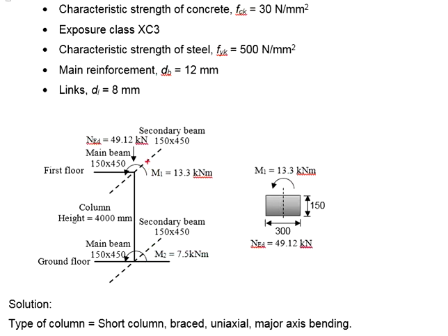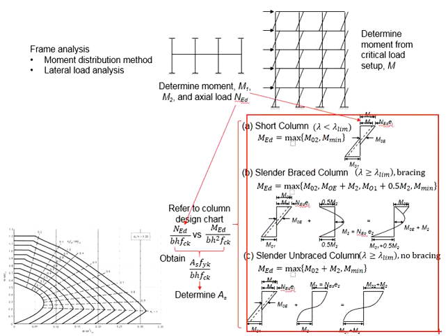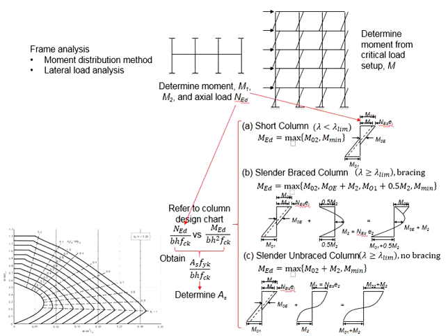However, these are the moments acting onto the columns. We are unable to take this moment directly as the design moment. This is because there may be other factors governing the design moment. Instead of using the moment acquired directly, we will need to go through a process of determining the MED before substituting into the equations and referring to the column design chart.